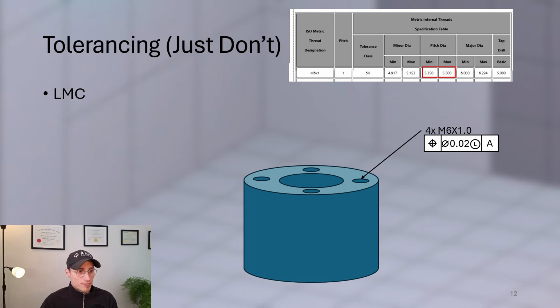So it really seems like this would be very risky. If your reliability is based on maintaining some thin wall between a threaded feature and a pressure boundary, it just seems like a recipe for disaster. I would highly, highly recommend, if you are considering putting LMC on a threaded feature, that you try to do a little bit of a redesign.